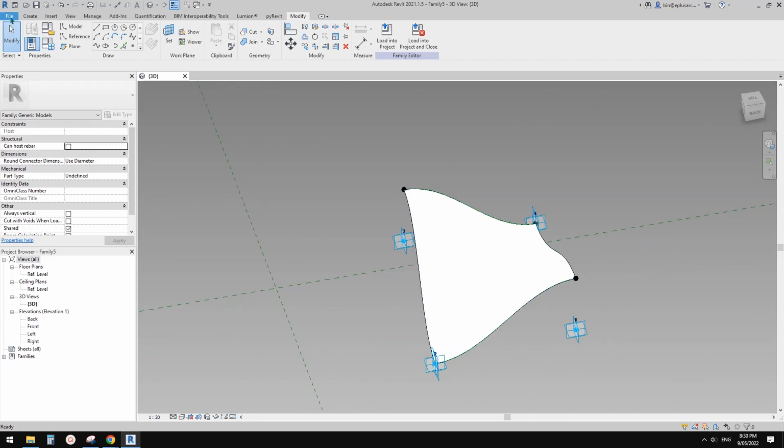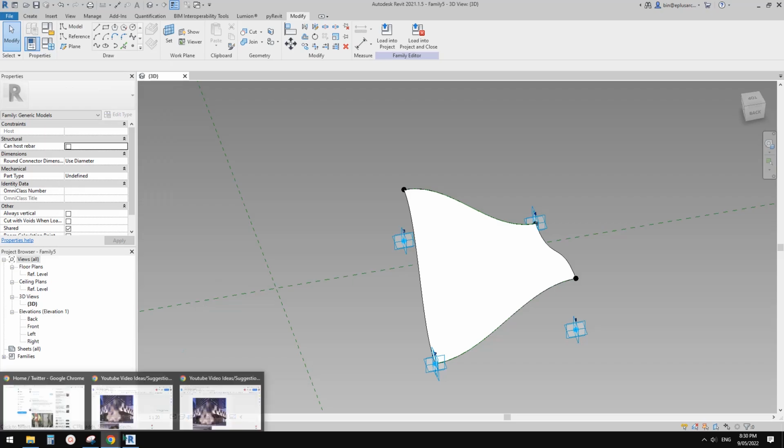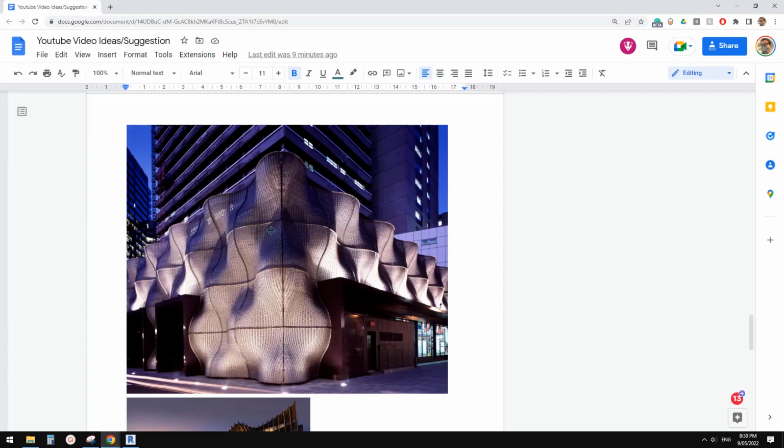And then the next step is, if you look at this, we need to find a repeating pattern. So in this one, you can't use this one because that's mirrored. So from this to this is mirrored. So we need to use this one. So 4 of these panels to create a pattern based. So this one and this one. So you can see repeat.